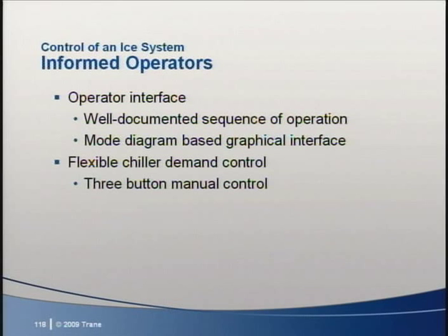The only way I know to combat this is to leave behind a well-documented system and a well-designed operator interface, one that informs and engages the operator with the system. In the past year, I've seen two innovative ways to accomplish this. The first is to specify that the controls vendor embed the same mode diagrams we've just been looking at into the operator interface. As the system switches from one mode to another, the system diagram in the control system changes to show the operator exactly what's happening. It really informs and engages the operator.